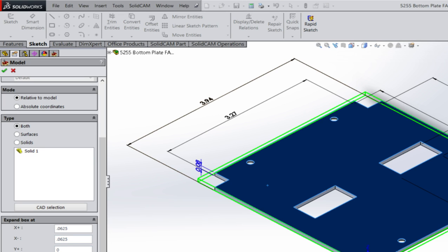So the parity, the plus and minus sign, is already inferred by the parameter box. You'll see it opened that up. Also wanted a 1/16 on the Y, both directions, but not on the Z, because I'm just going to use the material thickness I had.